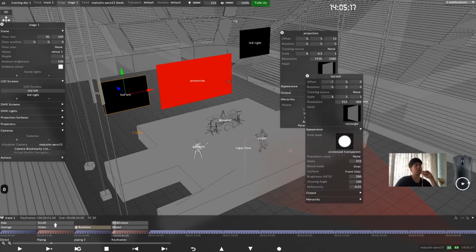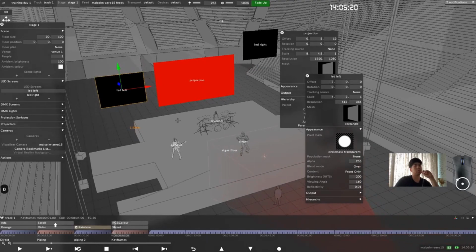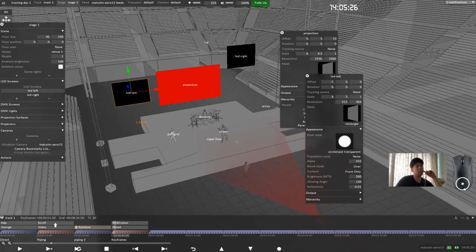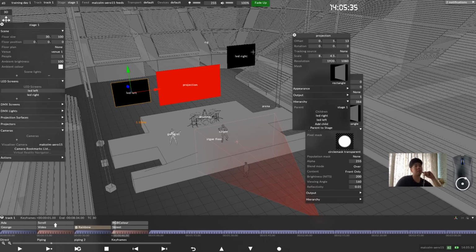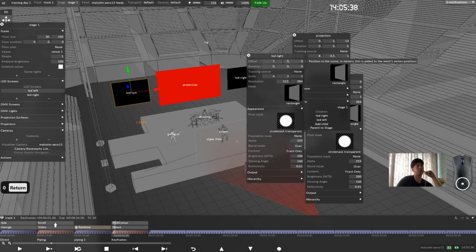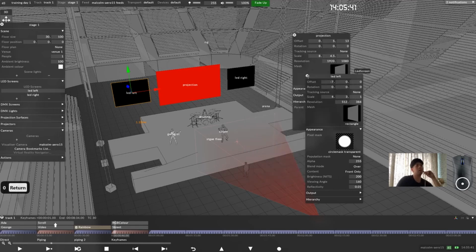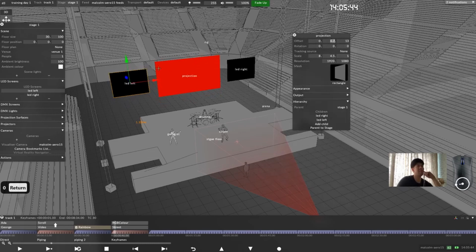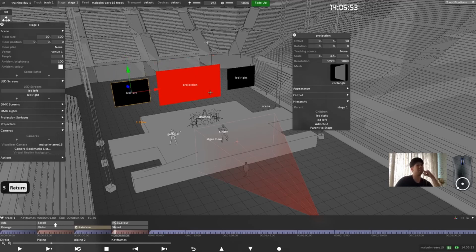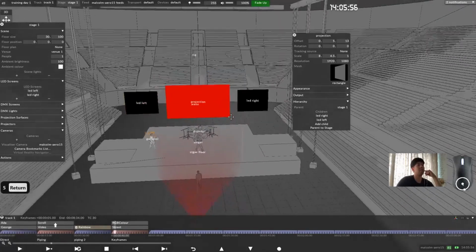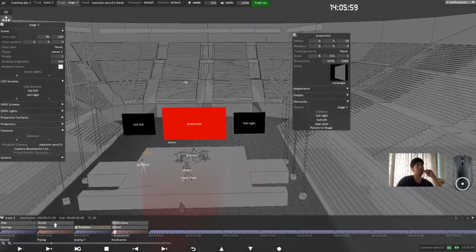it will be 0 level with the projection screen, because previously all objects that you place in Disguise, you'll take the origin reference point from the stage, which is 0 in the middle. Okay, so same thing, my right screen, I offset the height to 0. So right now if I move my projection screen, you can see 3 of these will move together. Okay, so we have made this screen itself, which is nice.